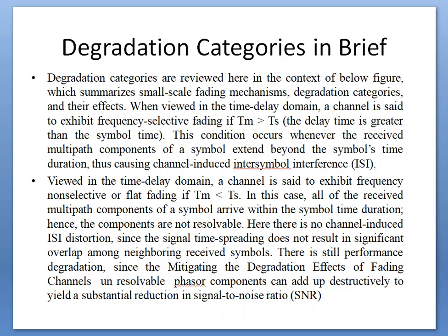Viewed in the time domain, a channel is said to exhibit frequency non-selective or flat fading if Tm is less than Ts. In this case, all the received multipath components of a symbol arrive within the symbol time duration. Hence, the components are not resolvable.